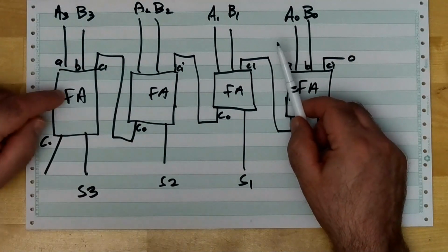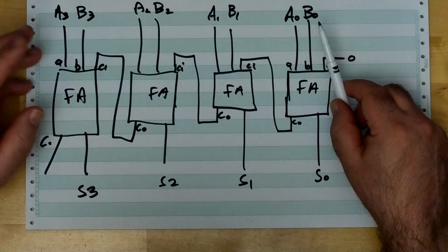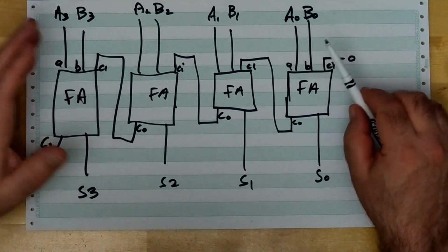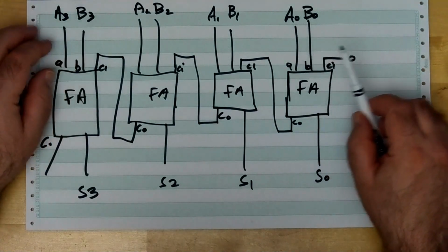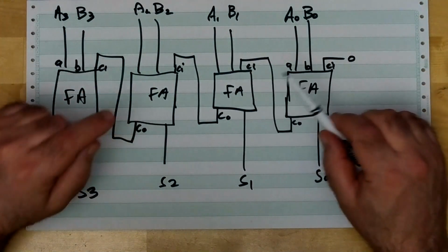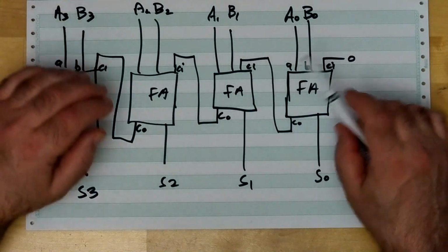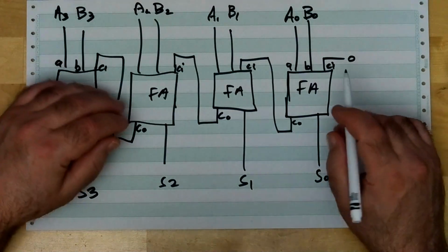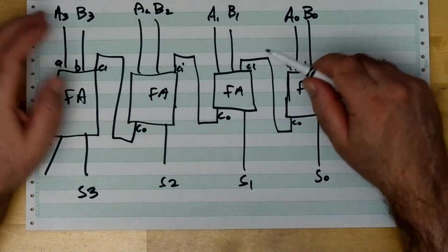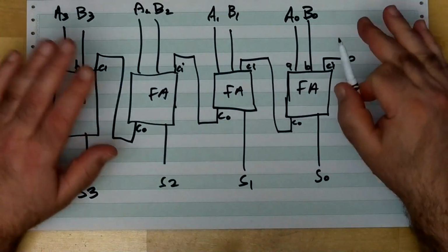And the length of this carry chain is proportional to how long it will take for this thing to do its job. So if you're going to add two 64-bit numbers together, you'll notice it takes twice as long as it would to add two 32-bit numbers together. If you use a schematic like this, there's other ways to make adders that work faster. They're called look-ahead carry adders. You can Google this. I'll bet there's a look-ahead carry webpage in Wikipedia specifically on this topic.